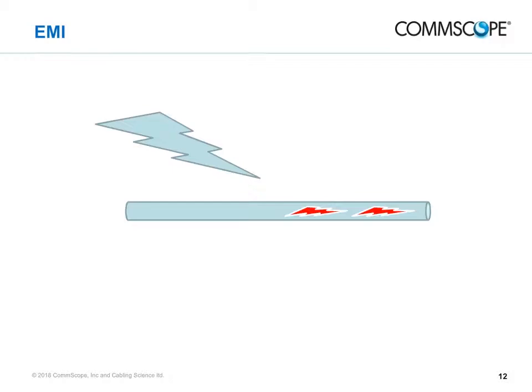Capacitive coupling occurs when two closely spaced conductors act like the surfaces of a capacitor. Increases in charge on one conductor will cause a corresponding increase in the opposite polarity charge on the other conductor. Inductive coupling is caused by a phenomenon similar to those behind self-inductance. It is the result of magnetic fields generated by current flow in one conductor, causing a magnetic field that induces current in another conductor. Radio frequency interference occurs when conductors act like antennas to receive radiated electromagnetic fields.